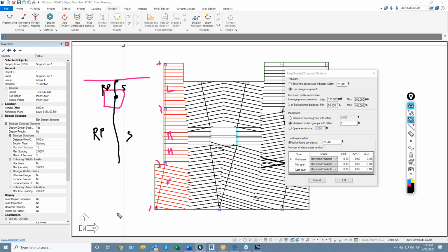Really, the cable, if I flatten out the drawing of it, the cable here might be low, and then it would just exit out of the slab at the CG here. So you'll have to go back and edit that after you've mapped. That's something that's pretty common if you're creating those 2 points, which in the past was a legitimate requirement if you didn't want to add a bunch of splitters to generate the design tributaries. So keep that in mind. Let's just use this as the default.